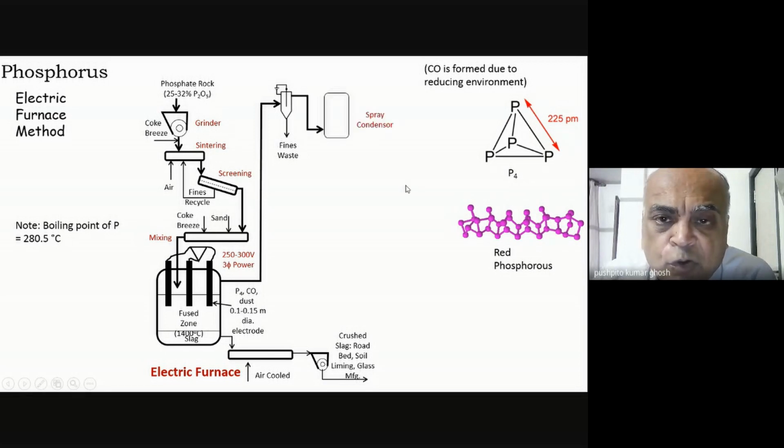And then, it's hot. Of course, it's coming out around 1400 degrees. So what one does over here is spray water on the gas mixture. Now, what else is there? There is CO, which will be formed. There will be CO2, and maybe even some HF and stuff like that might be present.